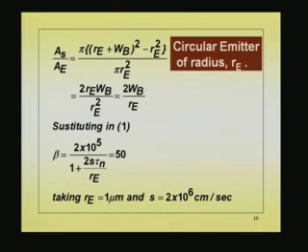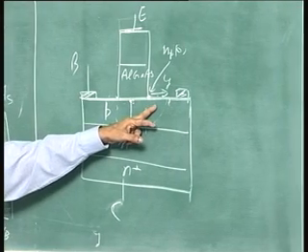But what they did in BL is, once they saw this, they realized that the effect is due to surface, because you do not see it in silicon, even in small area devices, and they tried to passivate the surface. The surface recombination velocity is large because there are a lot of dangling bonds here.